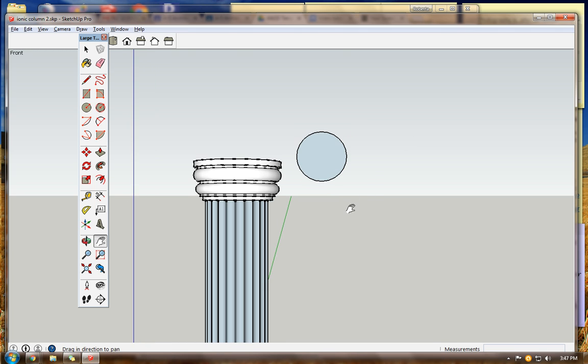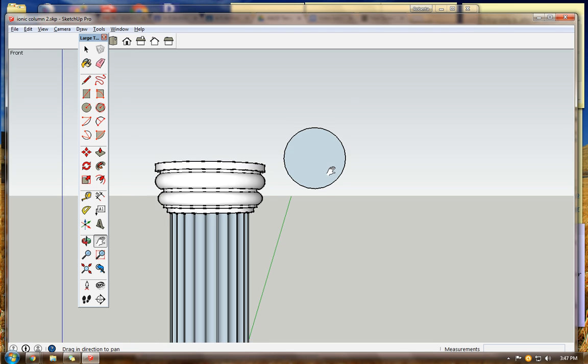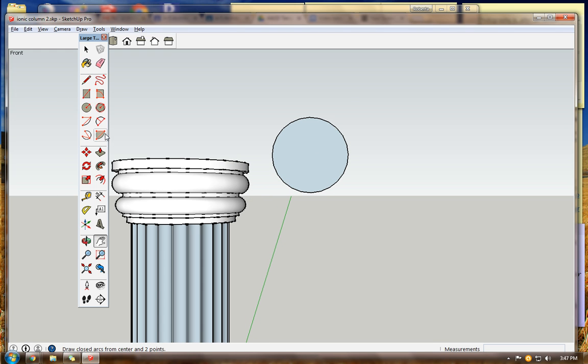so I'm going to take this circle and use it for now, but we'll do something about the size. We will select the outer rim of the circle and use the offset tool and pull out another rim at about 7 inches from there.